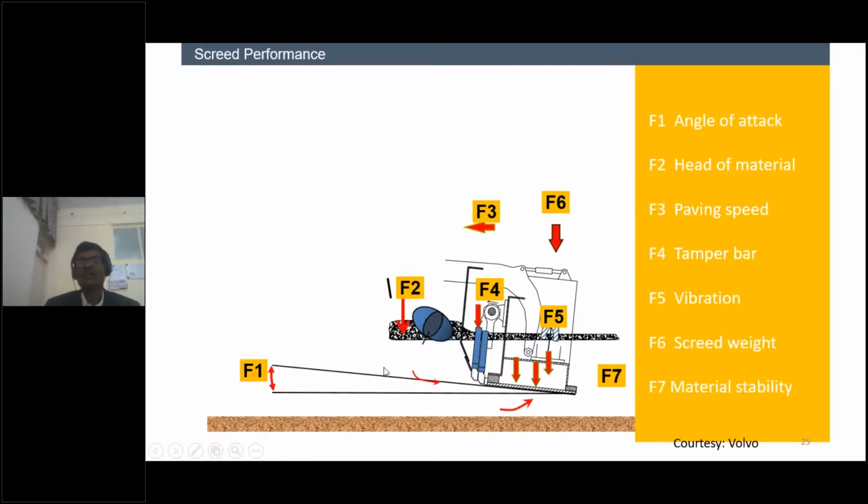The speed is to be maintained, and vibrations are to be maintained in the paver. Many times people don't put vibrations, and I have seen that many times. Heating of the screed is another important point. Many times people keep operating this paver, especially when inspection authorities go to the site, and suddenly they increase the lift thickness, layer thickness, and sometimes they decrease it.